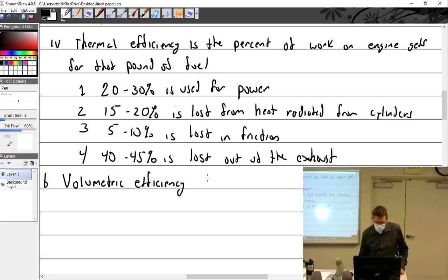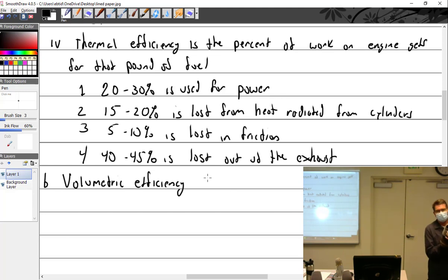And this is where a lot of attention is focused in cars, aircraft, everything. How do we increase this volumetric efficiency? Volumetric efficiency is really saying that we've got this piston going up and down in here, right? Here's my exhaust port, and here's my intake port. So what's causing the fuel and air to go into the cylinder to begin with? Well, it's kind of like a plunger. This thing pulls back. It's got rings in there.